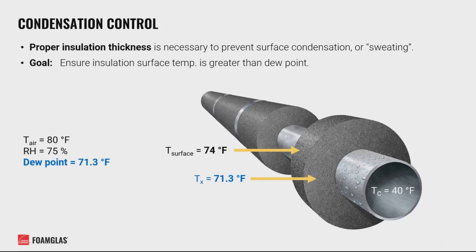One thing I'd like to mention is that even in this scenario, there exists a point within the insulation thickness where the temperature falls to the dew point. However, as long as the system's vapor barrier remains intact, water vapor will not be able to penetrate to the point where it can freely condense.